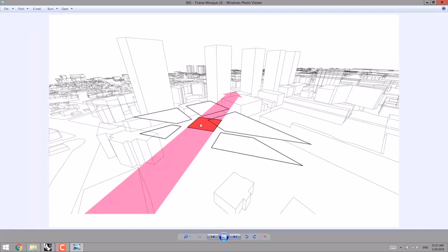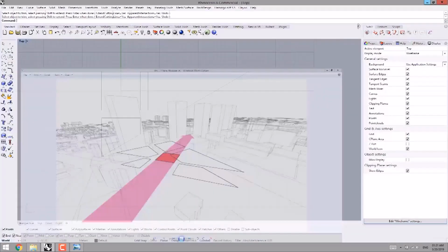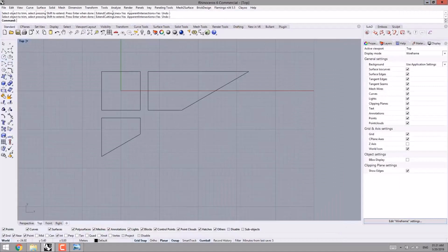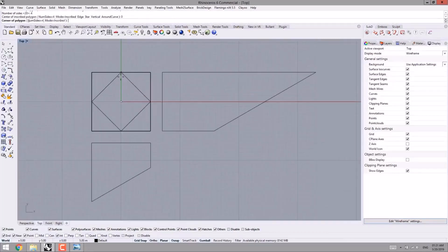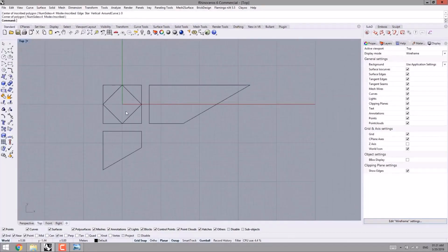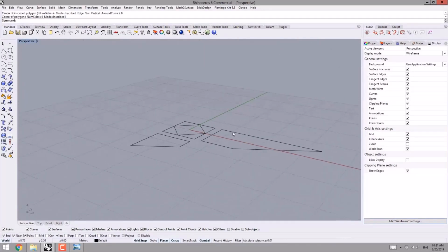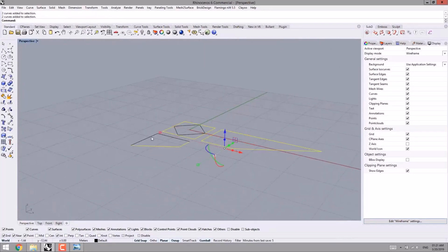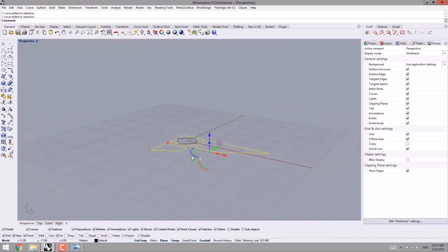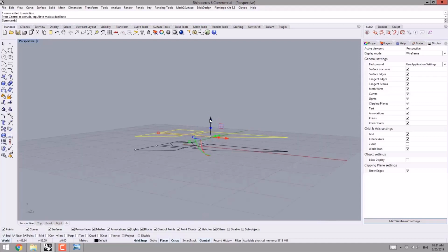then in the next diagrams, here we got a square which is highlighted in red, and it is rotated, and the dimensions of the square have changed. So I choose the polygon, then I choose 4 as the sides in the origin point by this way. Then I select these lines and hold down Alt to make a copy.